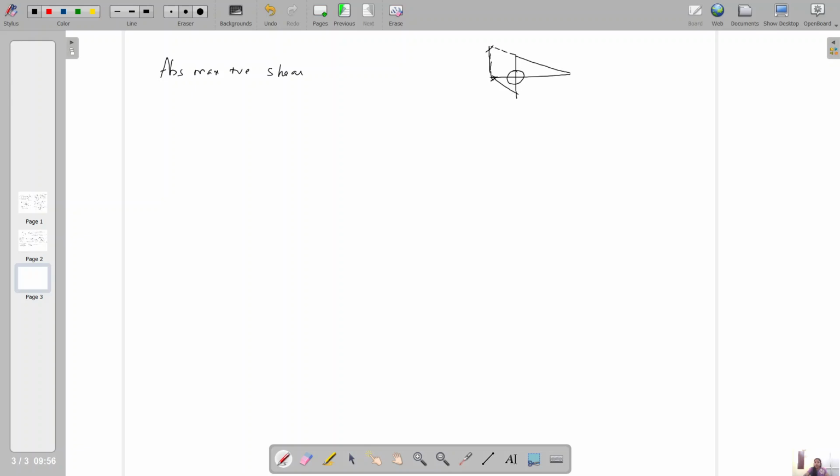So when you get this maximum ordinate, when you place the load directly at the support A, you can get the maximum positive shear force at A. The maximum ordinate of the shear force is equal to 1. So ILD for maximum positive shear force is this, and you superimpose the load 20 kilonewton. Obviously, you will get 20 kilonewton as the absolute maximum positive shear force.